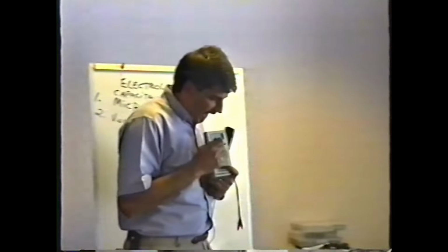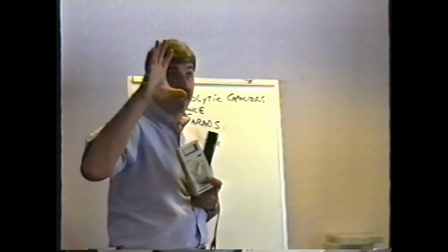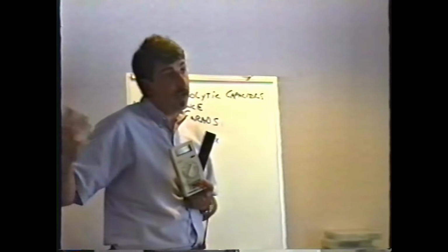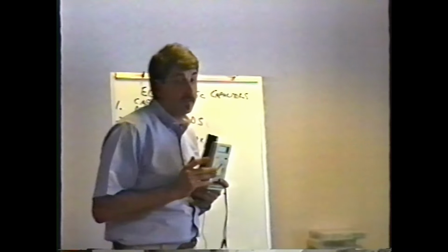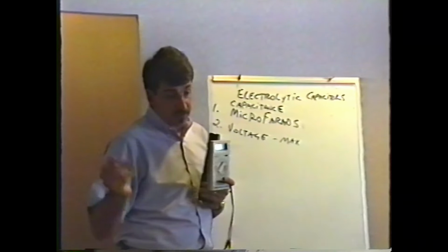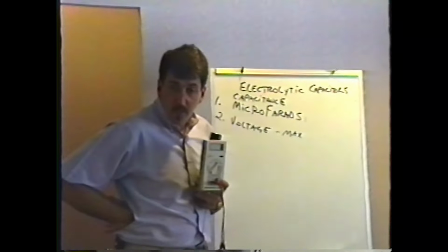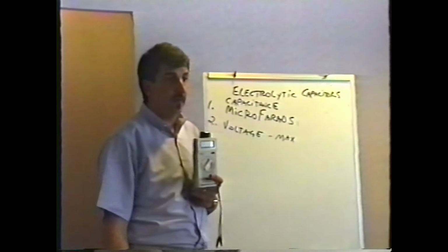Capacitors are usually not a catastrophic failure. Capacitors usually fail a little at a time. They start to get worse and worse and worse. And in a monitor, you see increasing amounts of distortion on the screen. In a power supply, for instance, in this one power supply, the Hytron style that I was mentioning before, it does the weirdest thing. You turn on the game and it doesn't come on right away. And then 5 minutes later, bing, it fires up by itself.